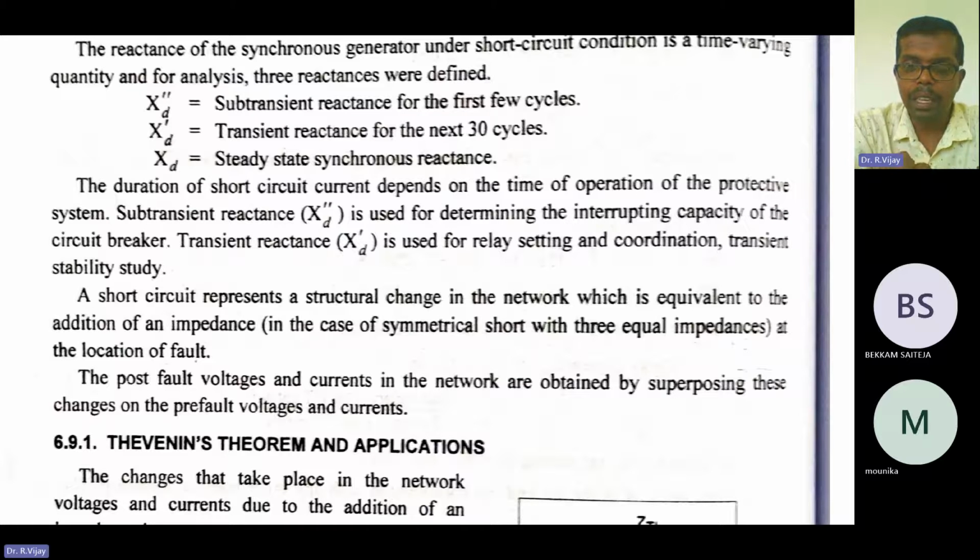Say for example, you're heating that particular conductor to a higher temperature. The conductor temperature might be 30, 40 or 50 degrees Celsius, and that may go to 500 or 1000 degrees Celsius for a few cycles, say 30 cycles. In that condition, the current carrying capacity of the conductor may be lost, so we need to replace that conductor sometimes.